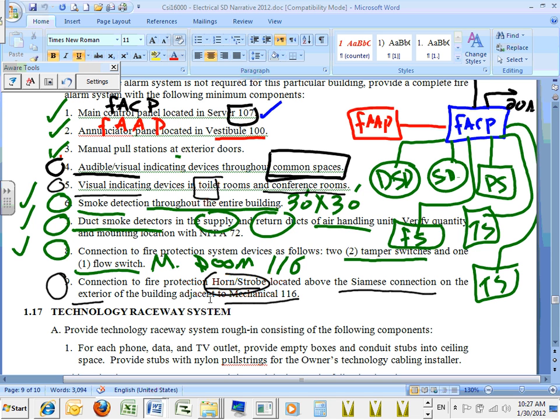Now, very important, Revit. Now let's talk Revit. Every time, if you guys came with me, because that's going to drive you nuts. Devices that are in the ceiling: if a device is going to be in the ceiling, listen to me carefully, make sure you put it in when you work in the lighting ceiling view that we did for lights. So go put them right next to the lights.